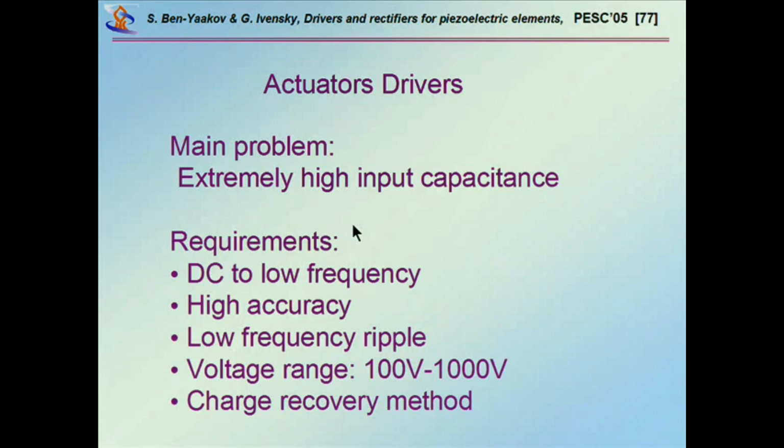The current has to be run at relatively high frequency for this capacitance, something around 1 kilohertz. So the current is, say, half an amp. Half an amp for the reactive current. The real current is maybe 20 milliamp. This is the whole thing. So most of the current is really capacitive, and it's a big issue of what to do with it.